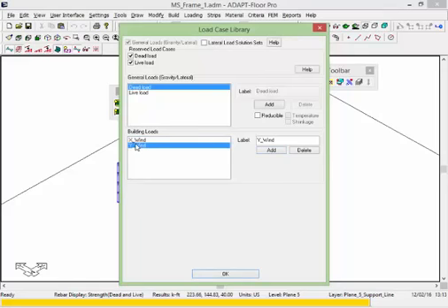The prerequisite for having a solution that will incorporate these load cases is you must analyze the frame in global or multi-story mode. So when we add these loads, we have to run the model in multi-level mode in order to get a solution. So we'll say OK to that.